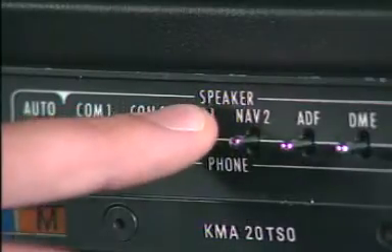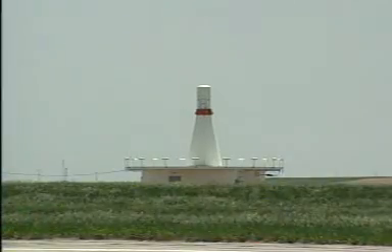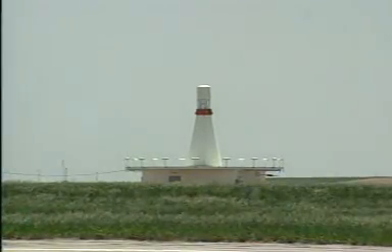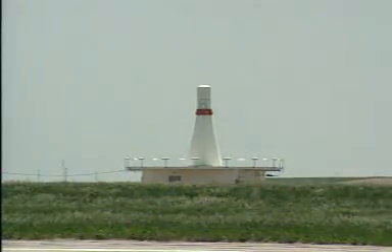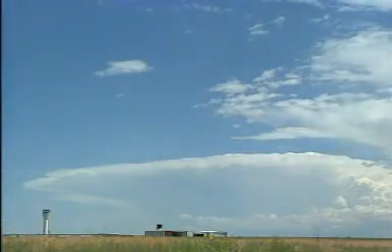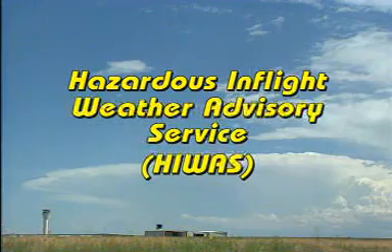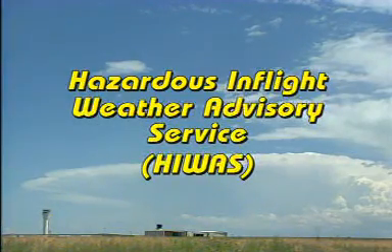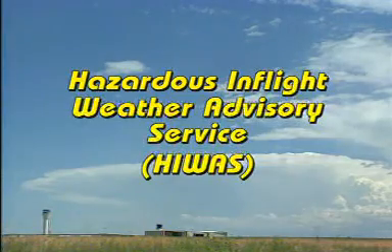You can also access weather data by monitoring selected VOR and NDB stations. These facilities normally provide local weather information updates or weather advisories. One such source of en route advisories is the Hazardous In-Flight Weather Advisory Service, or HIWAS, which is continuously broadcast over selected VORs.